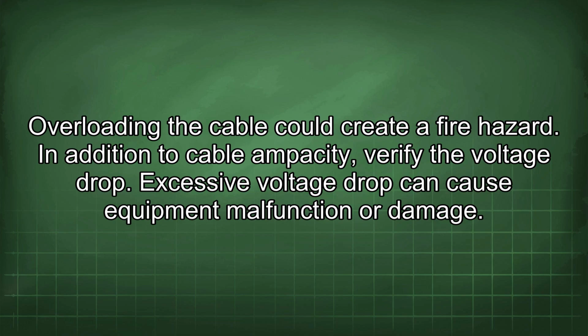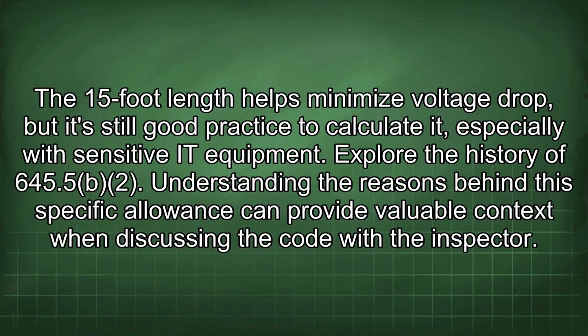In addition to cable ampacity, verify the voltage drop. Excessive voltage drop can cause equipment malfunction or damage. The 15-foot length helps minimize voltage drop, but it's still good practice to calculate it, especially with sensitive IT equipment.